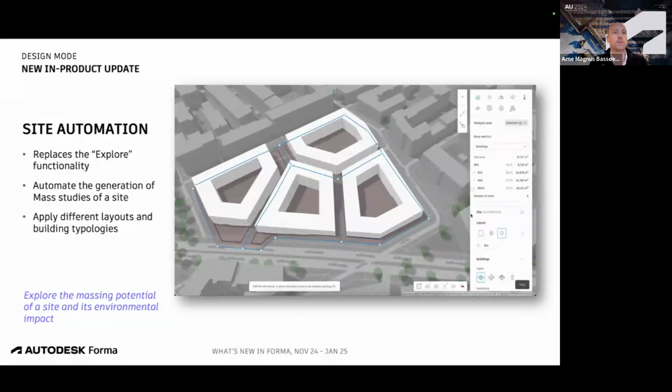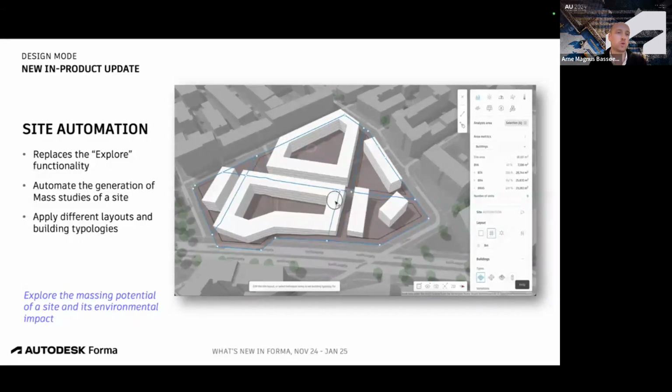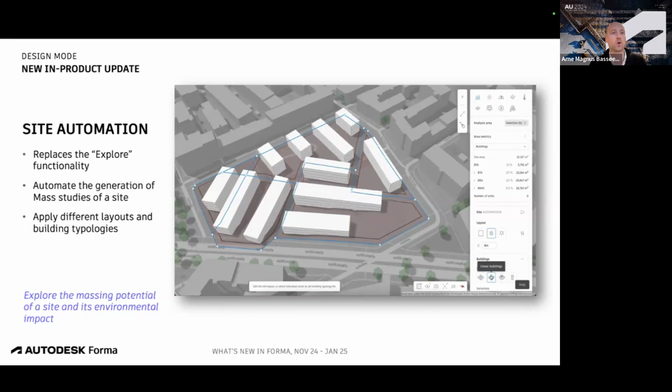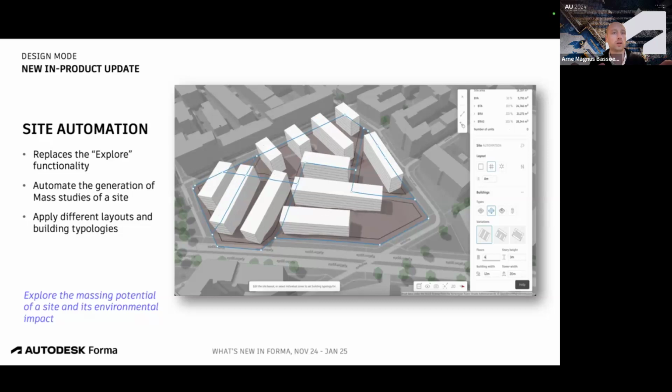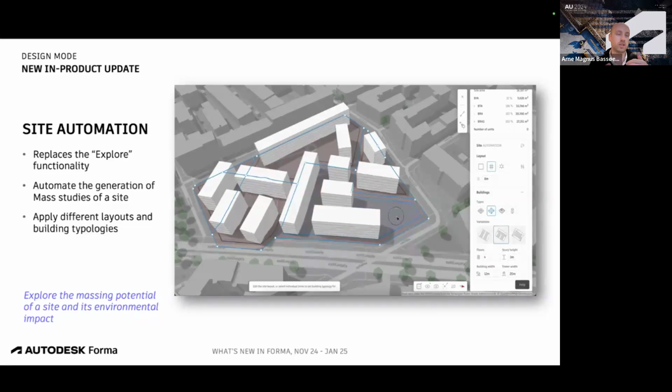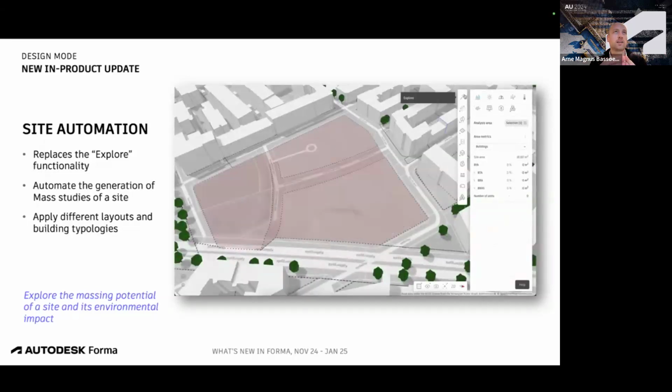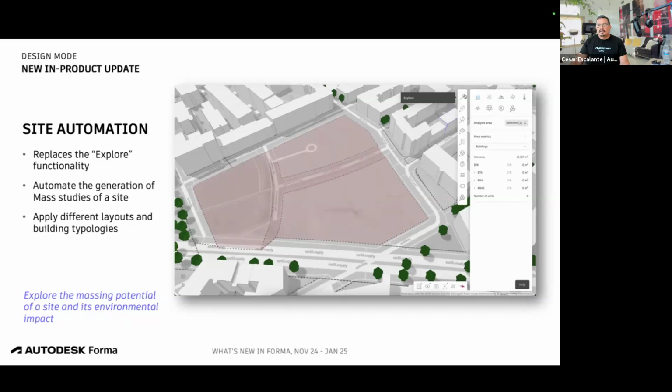One thing that is quite cool with the new road tool is that in the migration, we actually migrated all your projects into this new model. So even though you have roads in your projects that are square and have very hard edges, you can just double click that road and straight from there add the radius to those roads. So you don't need to draw them again to do that. Yeah, kudos to this improvement that was largely requested by our community.